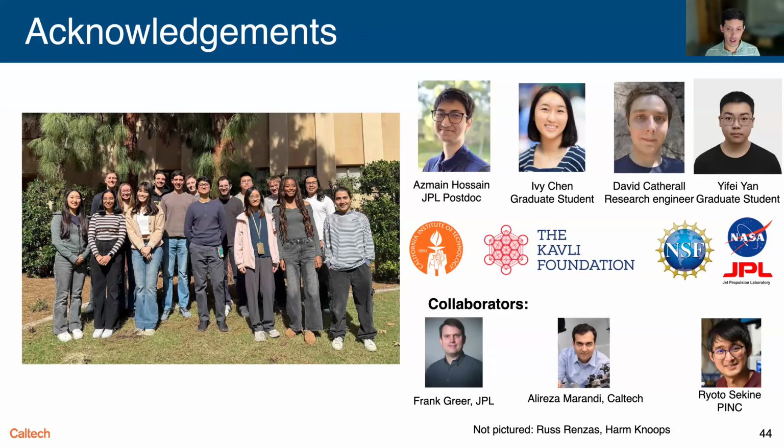So the various options are like, for lithium niobate, you could apply our process to smooth the sidewall. Then you could do a short RCA dip to essentially remove whatever gunk is left over. And then you'll arrive at the same surface in terms of composition you had originally, but it'll be smoother. So there are strategies like that. Yeah, that makes total sense.